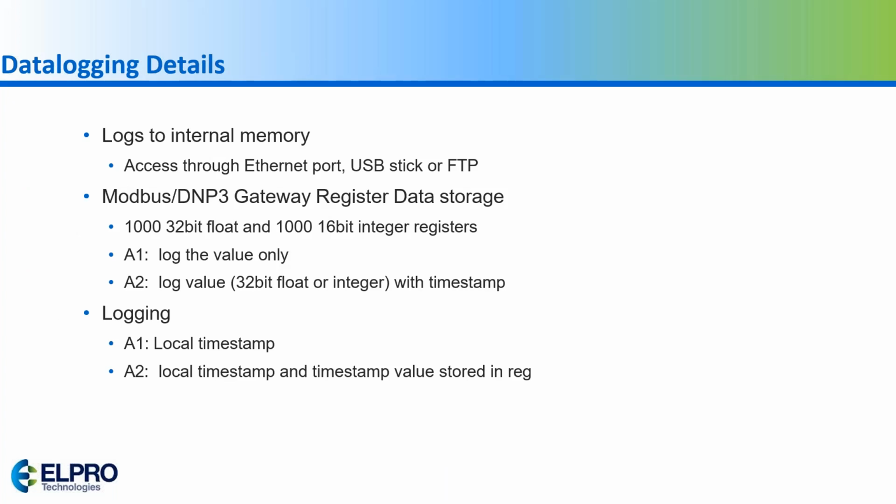It does have the capability of data logging, so it can data log internally. You can actually data log into data storages over Modbus or DNP3. And with this data logging, it has the timestamp.